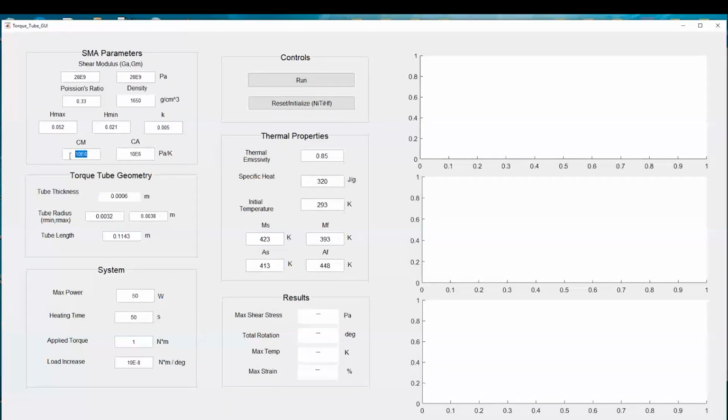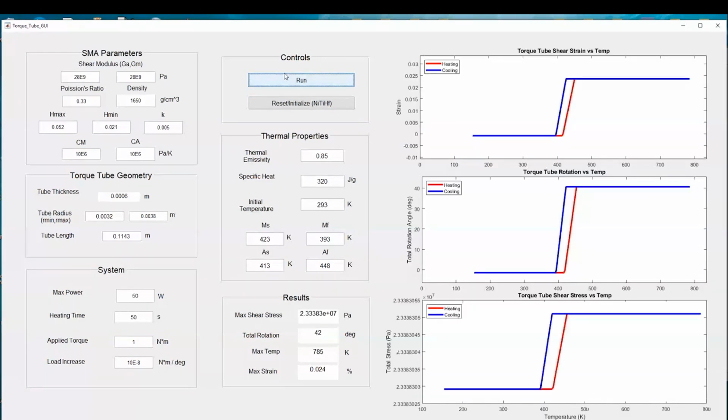And we also allow it to input some power. Sometimes we use induction, sometimes you will use cartridge heaters, but that boils down to some power in watts. Okay, and here are some thermal properties as far as emissivity and specific heats. And then once you run this model here, it does its prediction. It gives you a prediction based on this one. By the way, we gave it the calibration curves, right? Maximum strains, minimum strains, what I call those actuation plots, right?